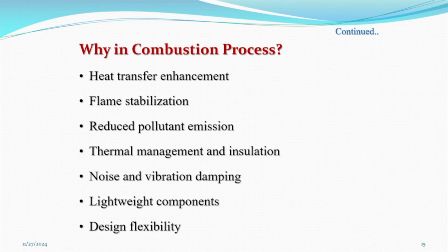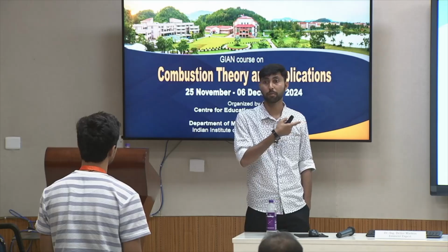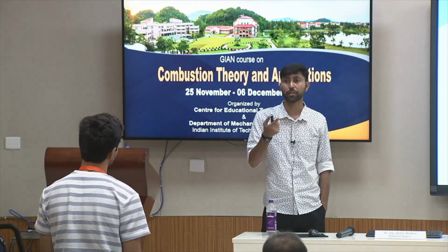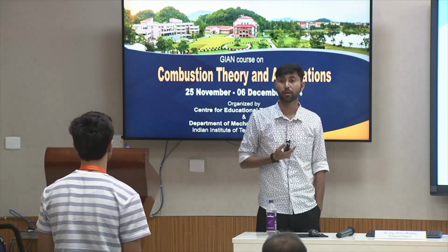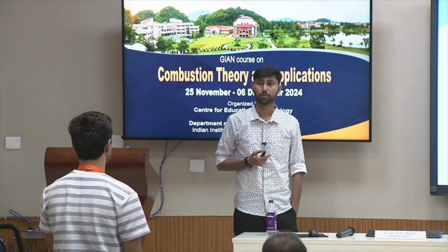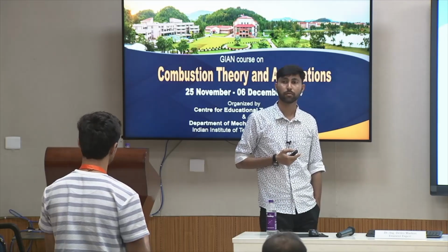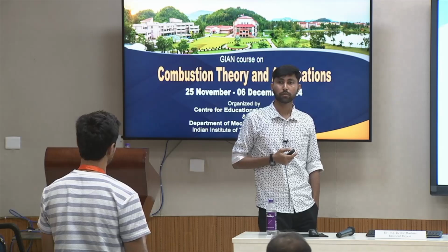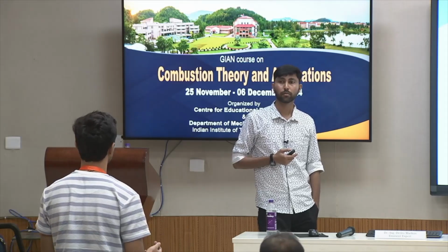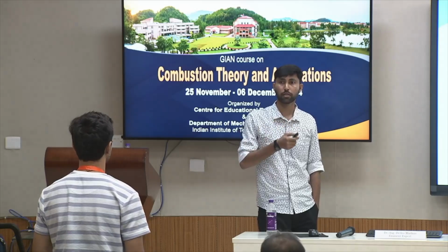See, this is metal foam. It also acts like a catalyst. So that is also one thing. Whatever the vibration damping, that can be converted into heat form also. Yeah, that's what I'm saying. If it is getting converted into heat and staying as heat energy in the ligaments of the porous material, that would affect the heat transfer rate, right? That's only going to increase the heat transfer performance.